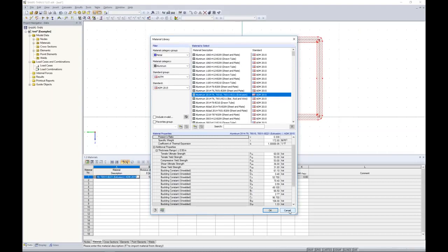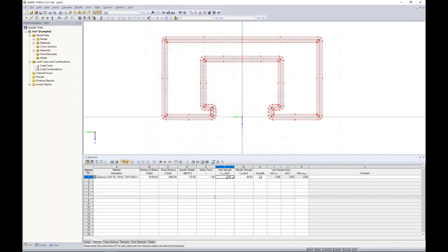So the program simply doesn't know what to use when calculating the plastic cross-section properties. So I can realistically set this to whatever, it doesn't matter, 35 and 40. The reason why is because I'm going to redefine the material once I get into RFEM. So for now, just as a placeholder, so to speak, we can now run the calculation with that applicable yield strength set in there.